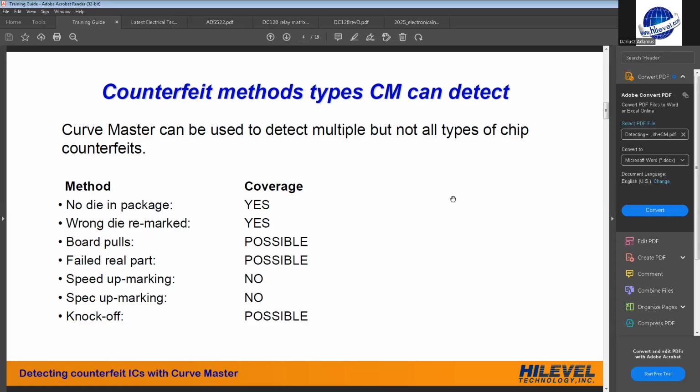So again, one of the benefits of using this curve tracer, especially in this batch mode, is that once you have everything set up, you can just ask a technician to do the testing for thousands of those chips because they don't need to have any specific knowledge. All they have to do is put a device in a socket, hit the start button, and if all is green, say, okay, this part is good. If it's red, discard it.